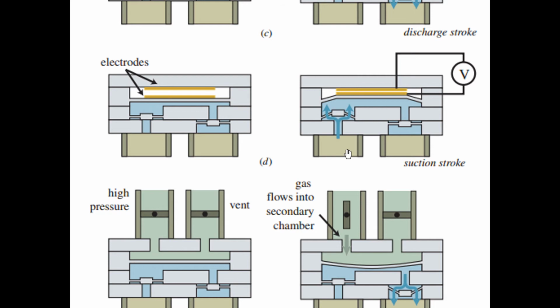If the distance between the electrodes is 10 times larger, even millimeters, let's say, or millimeters to centimeters, then the amount of voltage that you need in order to build up a sufficient electrostatic force between the plates is too high. It's actually greater than the dielectric breakdown of air, and you'd end up getting sparks between them instead of an attractive force.